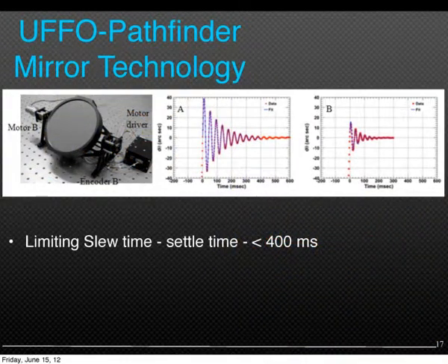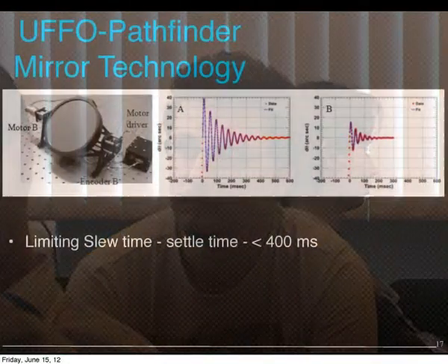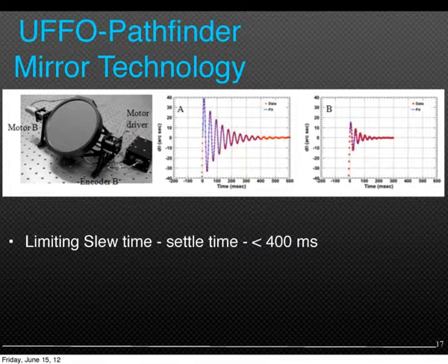So this is our beam steering mirror right here. And when you're talking about things in the 1 second slew range, what is limiting is not really how fast it takes to get there, but rather how fast it takes to settle. So if you look at our data here and the settling times, you'd see we get down to the arc-second range around 300, 400 milliseconds. So our fastest response will probably be around 400 milliseconds and up to about a second.